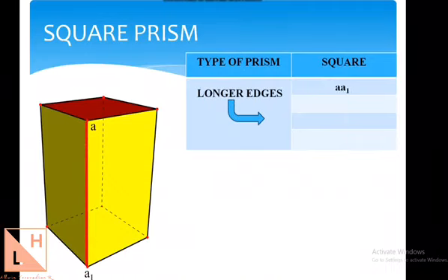that you'll find in a prism. Whatever the base side and the top edge side you have, say if it is 30 millimeters, this edge which is vertical will be of a larger number, maybe 50 millimeters or 60 millimeters. Usually that is how we find it for a square prism in your syllabus, and it is not mandated that it should be greater, it can be smaller as well. But if you refer to any problem in your syllabus in engineering graphics, we'll usually find the edge which is vertical will be the longest edge in that particular solid.